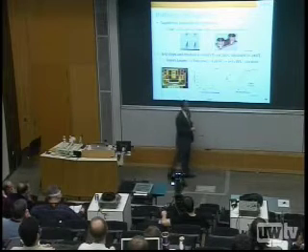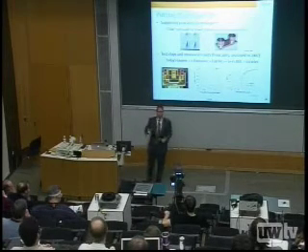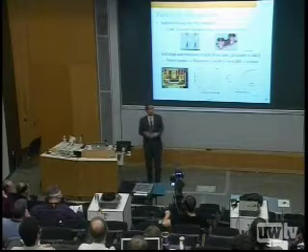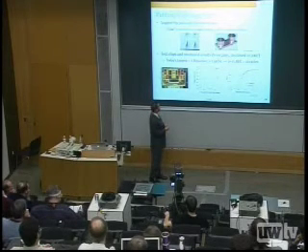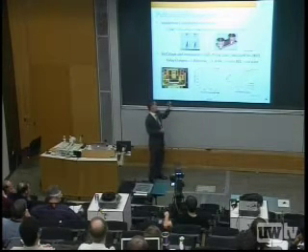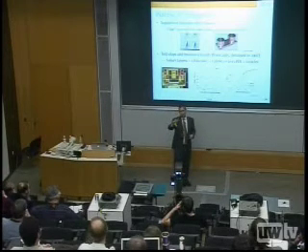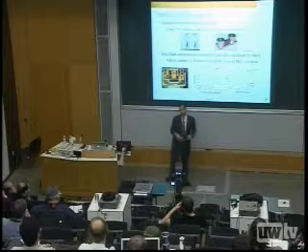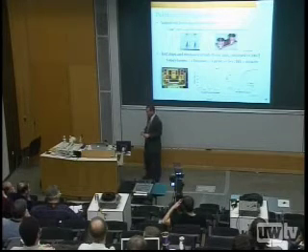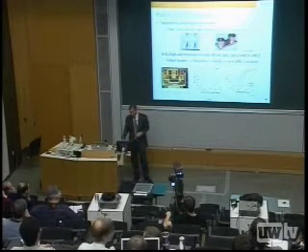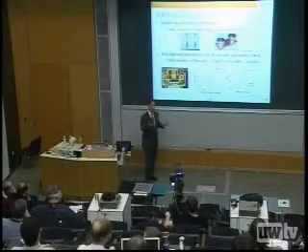It's actually sintered copper that has an inlet valve for water and an outlet valve for hot water. Those structures can cool about 3 kilowatts, well, not that particular one, but one from the same company, about 3 kilowatts on a 5 by 5 centimeter substrate, and that thing sells for under $200. So we have a lot of ancillary technologies that you can put around this communication system. But let's think of large-scale chips.